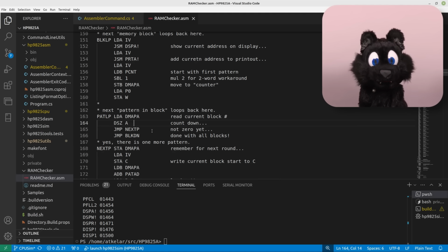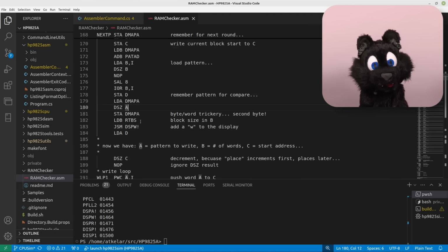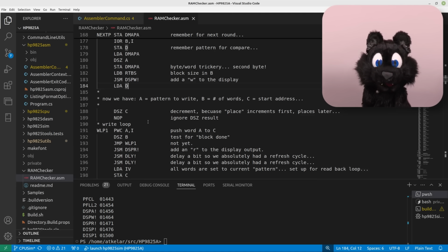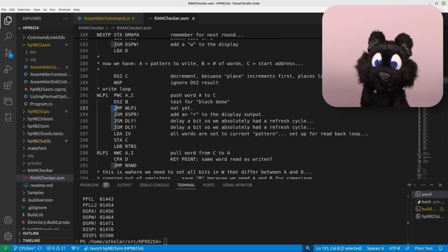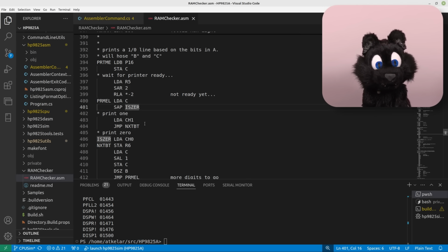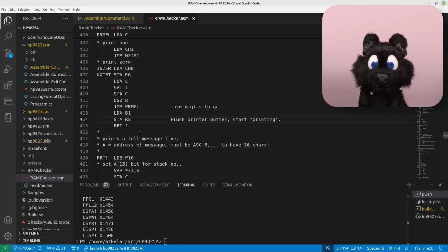And so, the memory test runs through the entire RAM space, and ROM, be careful to pull those out before running, and reports the failed bits in a string of marks on the printer, one for each memory block. So by counting the lines and columns of the failed bits, you know pretty much exactly where the fault is.